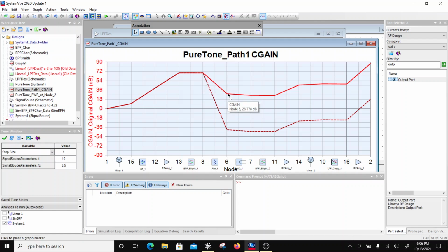So here, this is what a receiver is receiving, right? After putting in noise and everything, we are over here. So this is what a LNA is seeing. Okay, so here it is 25.6 and here it is 45.4. So LNA is 0.2 dB compressed here, right? And then mixer over here is 45.4 and this is 47.7. Okay, so again the mixer is 2 dB compressed here, 0.2 dB compressed here, right?